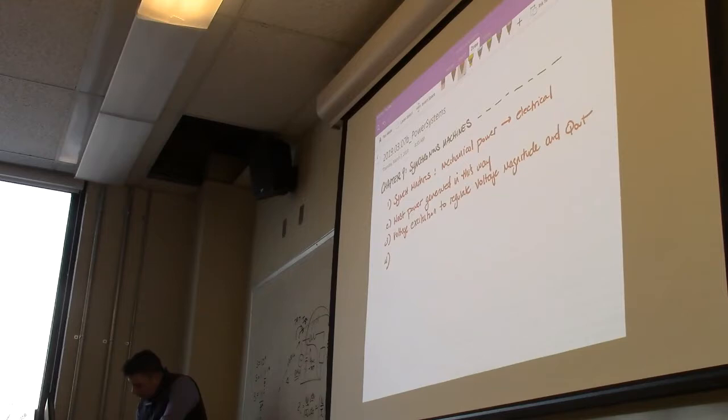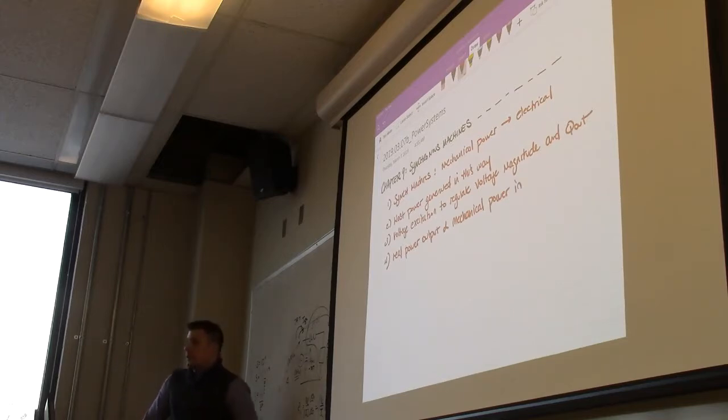And so the real power output is going to be proportional to the mechanical power in. Pretty straightforward relationship. If you want to get more power out of the generator, you turn up the heat, you start letting more steam into the turbine, and the mechanical torque that's applied to the rotor gets higher.